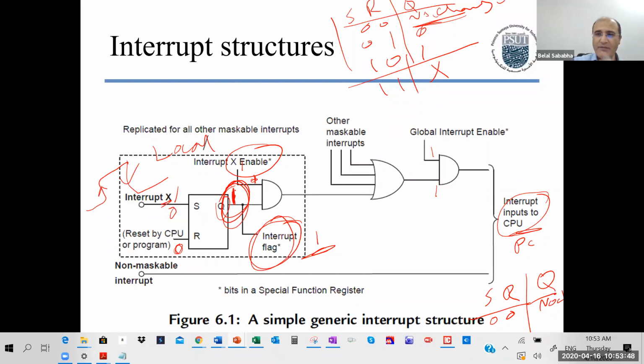This is very important because sometimes an interrupt could come in while you are doing something, serving another interrupt. You need to know if an interrupt happened while you're busy doing something more important. So this flag will stay raised. Then in your interrupt service routine, when you service the interrupt and you're done, you blinked, you did the buzzer or whatever, you go clear it. You write a 1 here, and you clear the flag. This will become a 0.